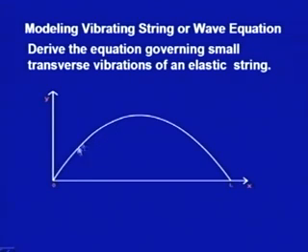And we want, at a particular time t, so what we are saying is this is my variable x, the vibration would actually be in this form and the deflection would be in this form. So, we want the solution u(x,t), that is, at a particular time t, at a particular point x, what will be the deflection, that is, what u(x,t) we would be interested to find if we had deflected or deformed it.